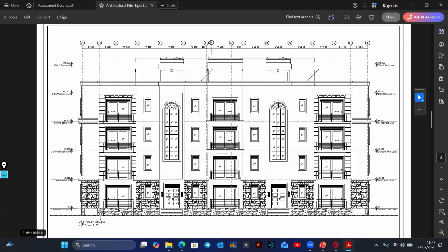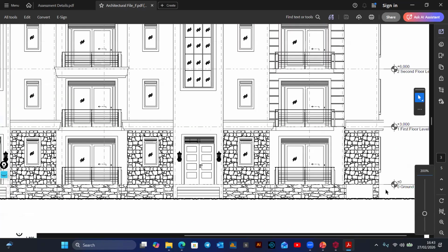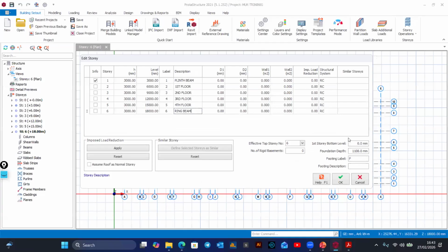this is ground. So we should expect to be like how this man represented it here. We should be at 0. This here, you should be at 0. So you also have to reduce your levels to indicate that at this point you have 0. How you achieve that, you need a negative distance within the ground, like you go into the foundation. So I'm going to have a negative distance of 1,500.